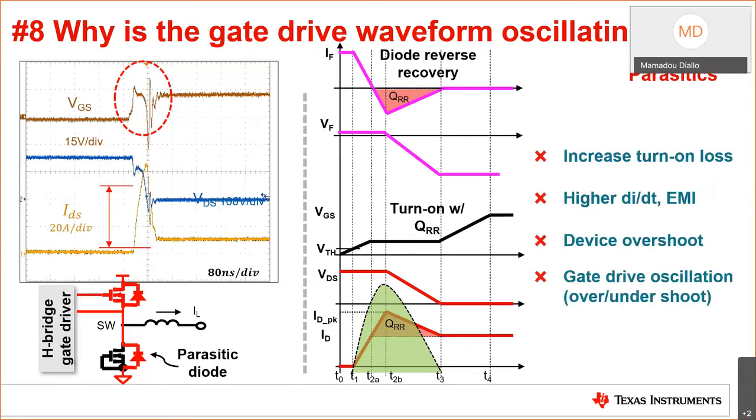The driver IC will typically overshoot in this scenario or cause EMI issues as well as ringing. For silicon MOSFET, the overshoot could be over 5 times that of a nominal switching current, while IGBTs have relatively smaller overshoot amplitudes. The main reason is the body diode, again, considered a parasitic diode and not really optimized for the reverse recovery times in hard switching applications.